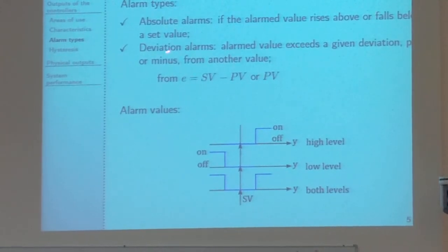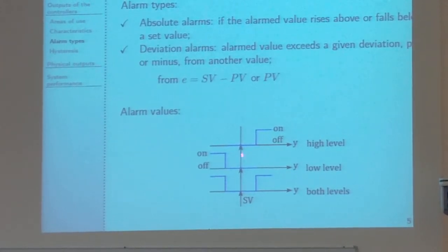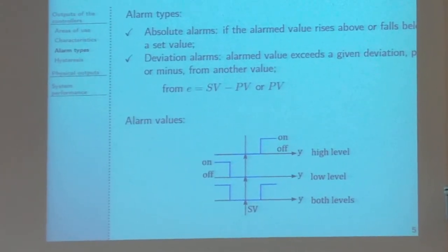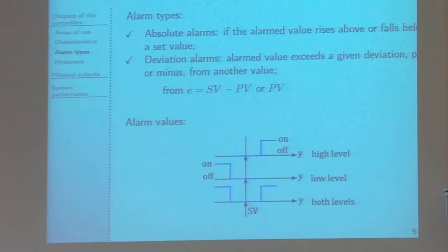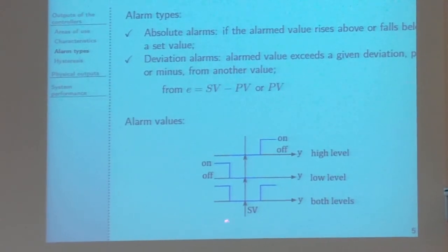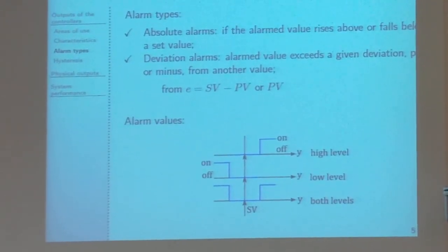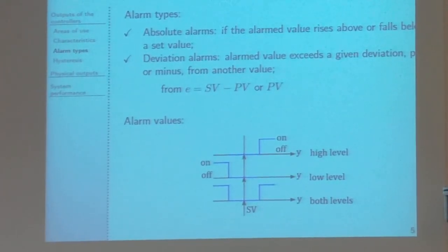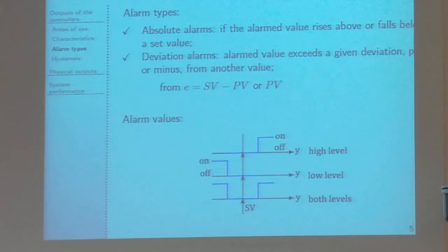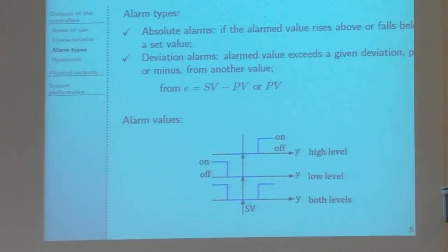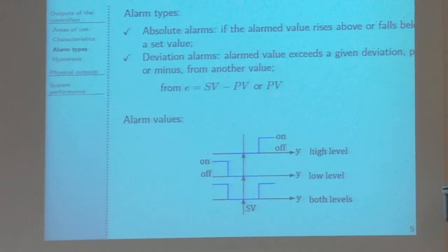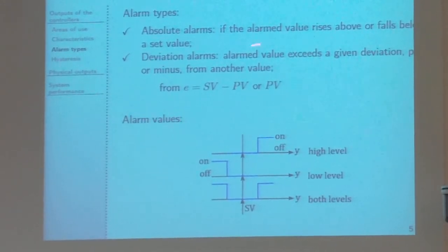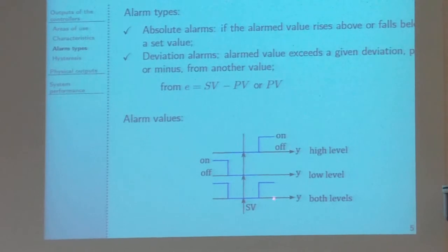The difference is that we are setting what is the initial value from which we are counting. Basically, as an initial value, we are taking, for example, our set point. If we talk about temperature, we say that our set point is our initial point. From that, we would like to see what is the difference to the present temperature. So we take an error between those.